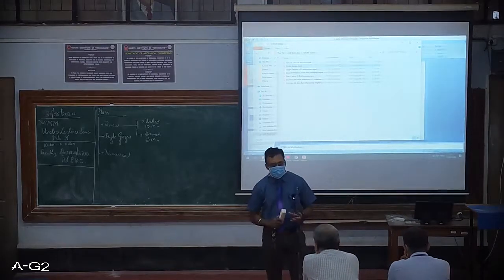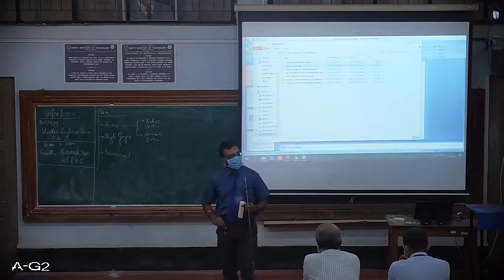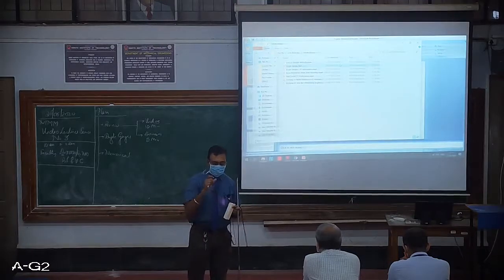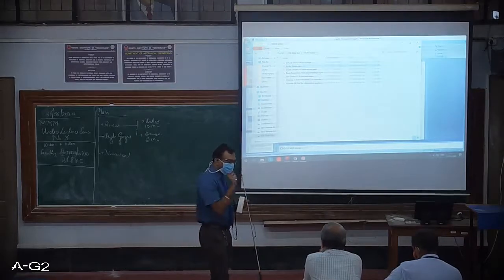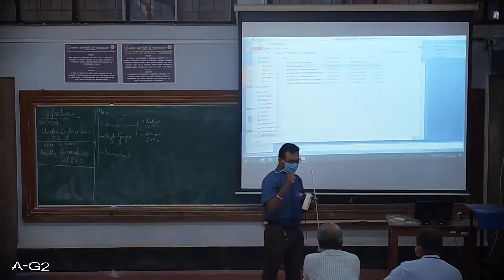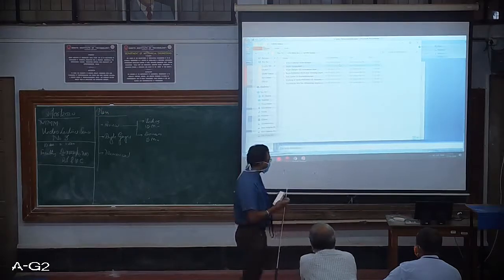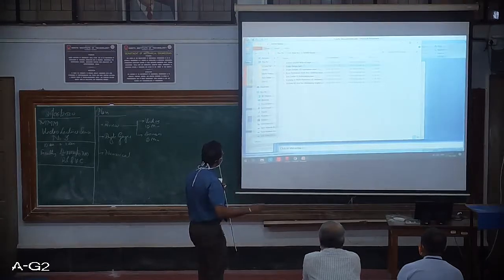So this is the way we should know the range of IT grades. And with respect to the sine bar, the surface is maintained at IT4. We also discussed the relief holes. The professor was discussing axis, parallelism, and what specifications are needed. All this was discussed.